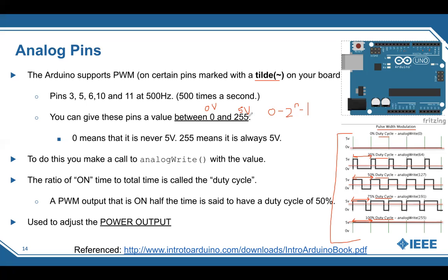So that's just based on binary. So the number of bits in here would then be 8 bits. So pretty interesting just how that number came into being. Okay, cool loop fact, but all you need to know is that 0 corresponds with 0 volts, and then 255 corresponds with 5 volts. So if you want 2.5 volts, just take a number in between. So that'd be like 127.